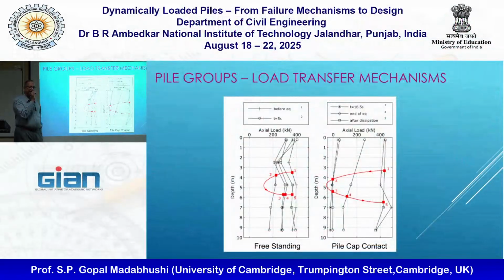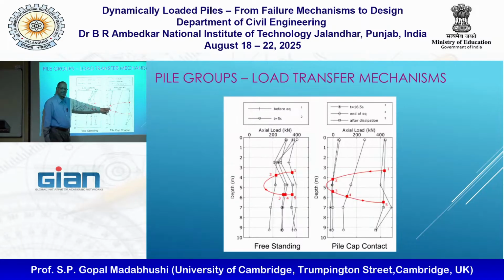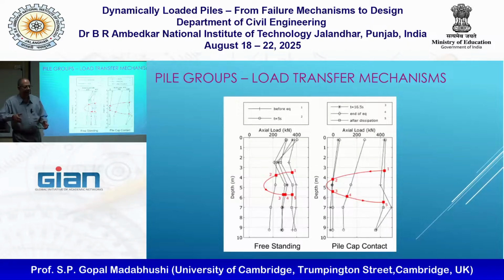And this is quite a revealing set of experiments. So here the settlement will be less, but you are basically relying on the pile cap. So what designers routinely ignore is what is saving them when this ground liquefies.